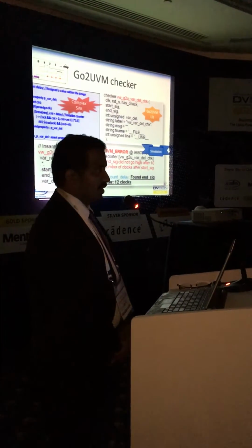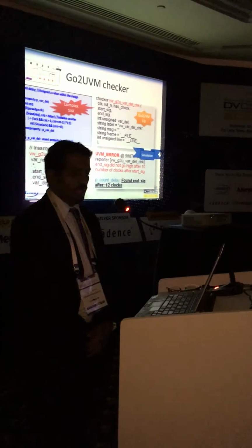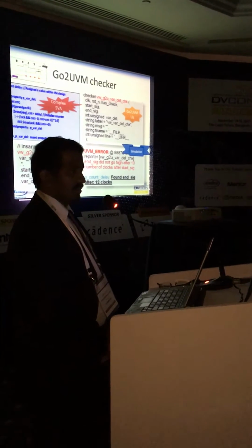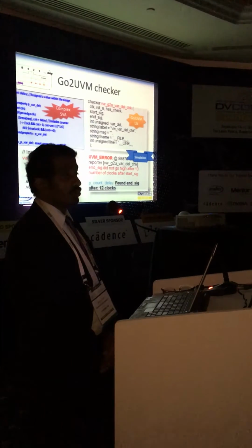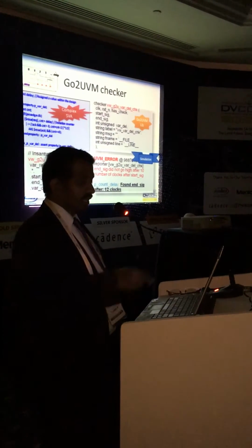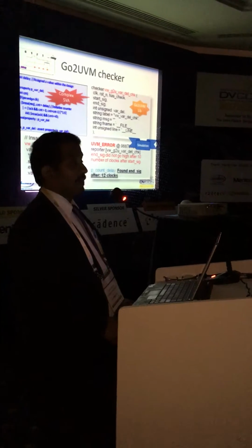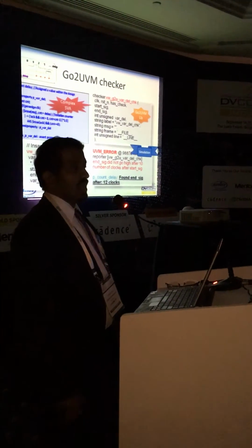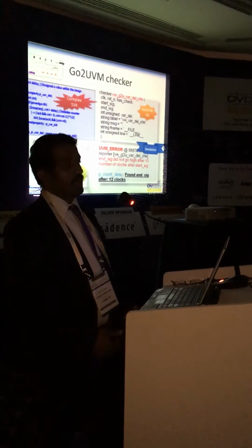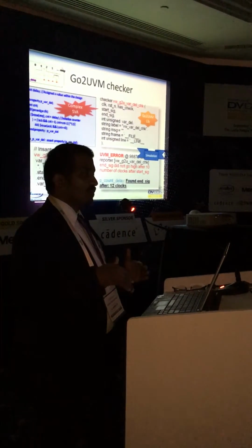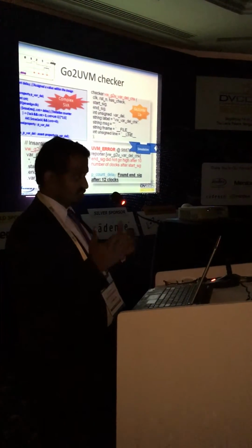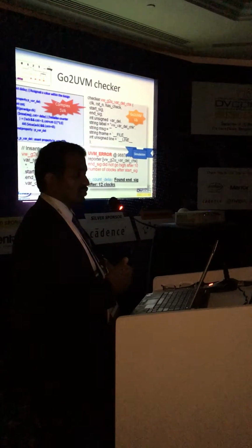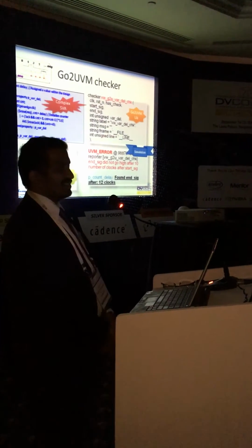So we could run simulation, and here are the two things that are going to happen. One, when the design fails, when the assertion fails, you're going to get a nice error message over there with the UVM error, so you're not going to miss it. The other problem with assertions: you write an assertion like that, and your UVM error will say, I'm happy, the test is passing. Know why? Because there is no action block over there, and the built-in $error would not trigger a UVM error. And for those who are looking at UVM day in and day out, you look for a summary called UVM errors, and you get a 0, and you thought the test is passing, but actually there was a failure in assertions. It wouldn't happen with the checker library because it's all built in.